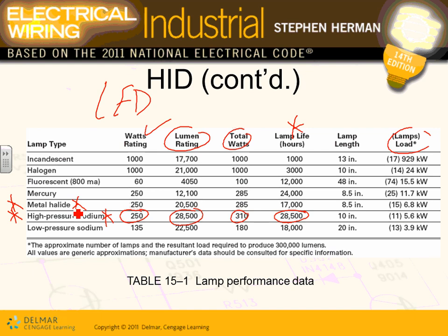It's a crime to leave here not knowing, if they tell you we're going to do a lighting and pick a lighting fixture, what type of fixture. The fixture of choice when you do a parking lot is metal halide or high pressure sodium. These are the optimum design for outside, taking into consideration the lumens per watt, the life expectancy of the fixtures, and the performance of the fixtures. Like we did when we did the commercial project, that was basically what we chose, metal halide or high pressure sodium.